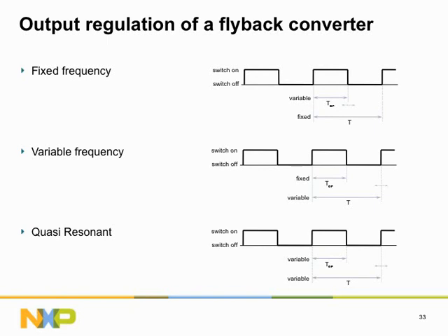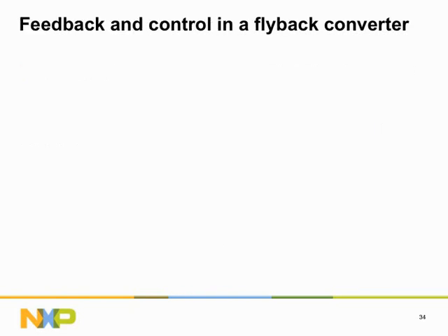It is the task of the SMPS controller IC to drive the switches in the switching network in such a way that the output is regulated in the desired way. Simple controllers will usually have just one operating strategy implemented, and more advanced controllers will change the control strategy dynamically. In order to regulate the output properly, an SMPS controller will need information about the output. Again, we will take the isolated Flyback converter as an example.